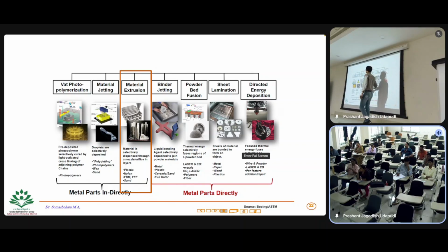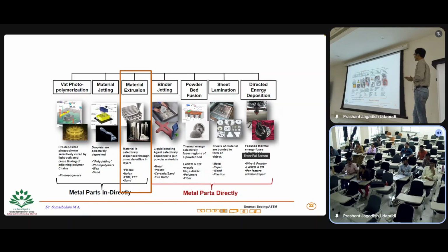But in powder bed fusion you need a lot of material. Imagine the bed area is 200 by 200 mm; every time you need to spread that much material over the whole area. Whereas in this case you don't need to spread, because the powder comes through the nozzle and the laser comes in the middle. Of course, there are variants. But again, you only fuse the material as soon as you put the powder on the substrate, and the laser comes and fuses it directly.